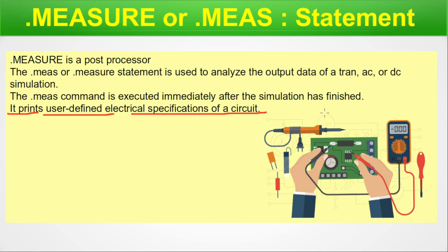What we do with SPICE is mostly used in VLSI electrical characterization. That's why the dot measure is a very important thing. From one simulator to another simulator, this dot measure can have different names. However, the purpose of the target will be the same.